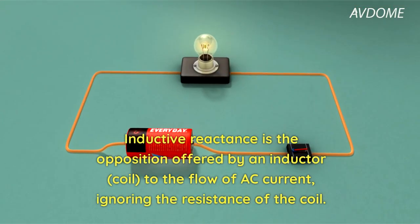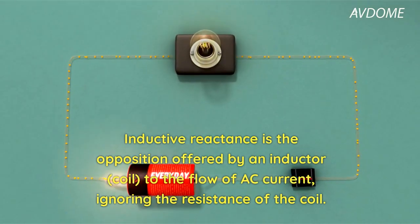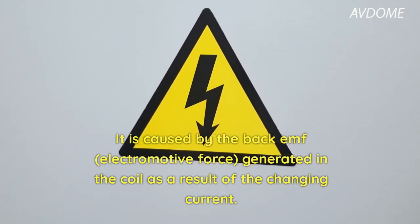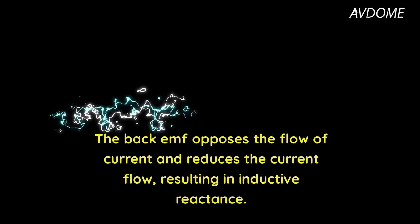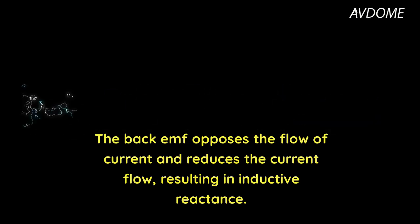It is C. Inductive reactance is the opposition offered by an inductor, coil, to the flow of AC current, ignoring the resistance of the coil. It is caused by the back EMF, electromotive force, generated in the coil as a result of the changing current. The back EMF opposes the flow of current and reduces the current flow, resulting in inductive reactance.